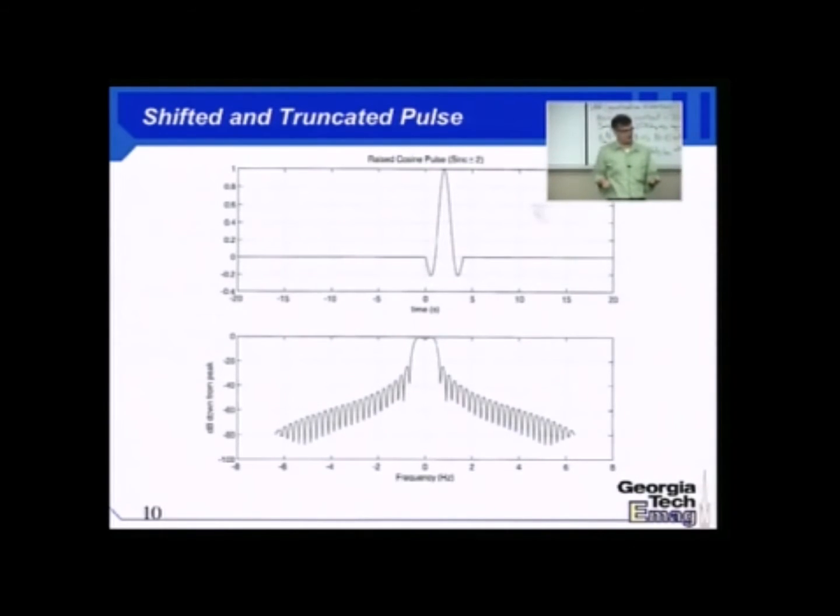Well, what are your options at this point? You have 2 options. You can either slow down your transmission. What does slowing down the transmission mean? That means I've got to take my pulse and I just stretch it out in time. I transmit fewer symbols per second, fewer bits per second. And that will, in the frequency domain, squish the spectrum. So now some of those large peaks are going to be brought within your allotted bandwidth, and you'll meet the regulatory agency's criterion.